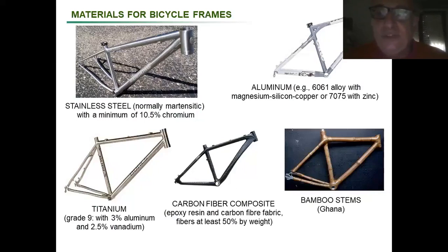And you may have stainless steel with a ferritic structure, therefore with alpha iron, with an austenitic structure, therefore with gamma iron, and with a martensitic one, which was subjected to some heat treatment of hardening and tempering, and then you get to this tetragonal structure. We discussed this already last time.